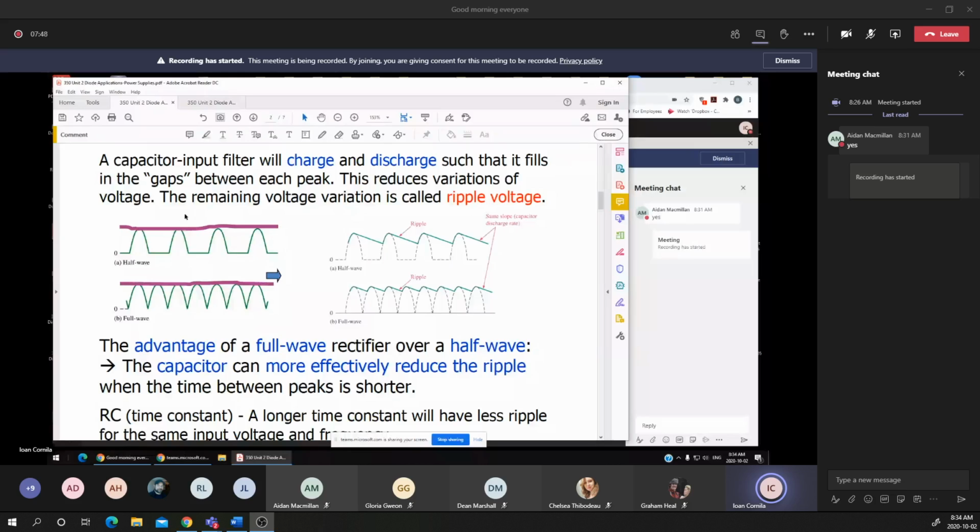Now, the big step we accomplished is that we made a DC voltage, but the second part is to make a smooth, straight line representing a DC voltage or a DC current. This means that for a full wave or half wave rectifier, the variation on the output voltage is between the peak voltage and zero voltage. Somehow we have to fill up the gap between the peak voltage.